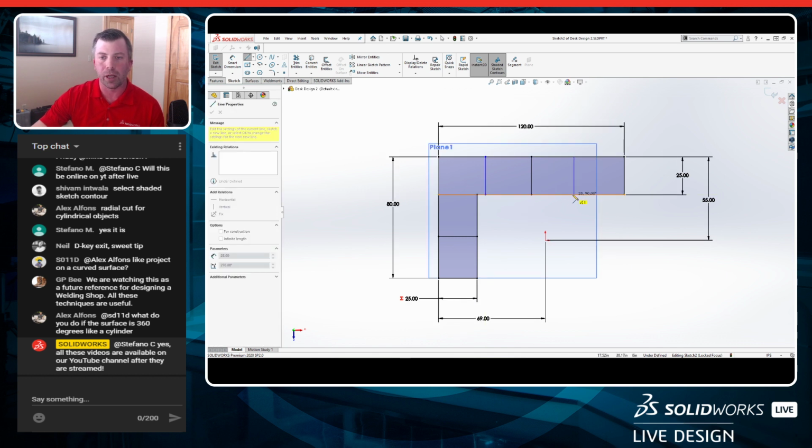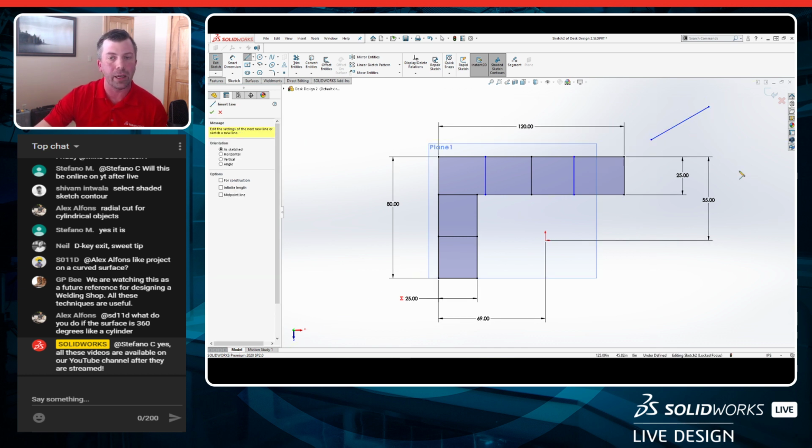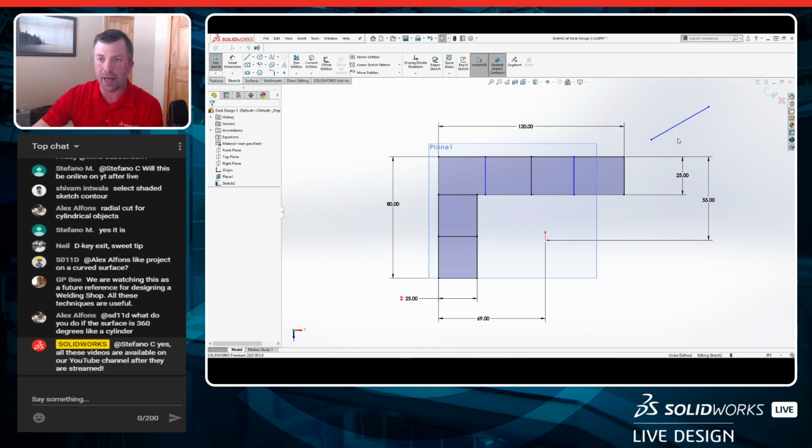Now I use a click, double click to draw my line. So 1, 2, and then double click to end it. The other alternative to that as well is you can just use a click hold to be able to draw that line. And when you release, it no longer creates that connecting section. So another little sketch pro tip for you.